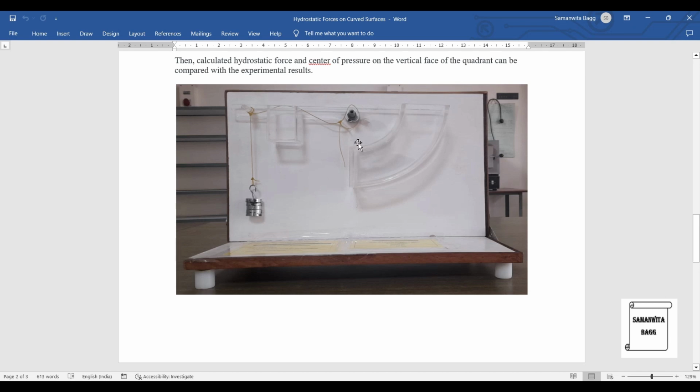Also, this fulcrum over here, this is a lever arrangement. It's like a seesaw movement. So when this lever is attached here, or this is a fulcrum here, at this point there could be some looseness of joint or some tight joint. So because of that, this weight adjustment could also give you some error in reading. So the most appropriate method generally used in research is the numerical method. Then you have these experimental results which you can use to tally your numerical results.